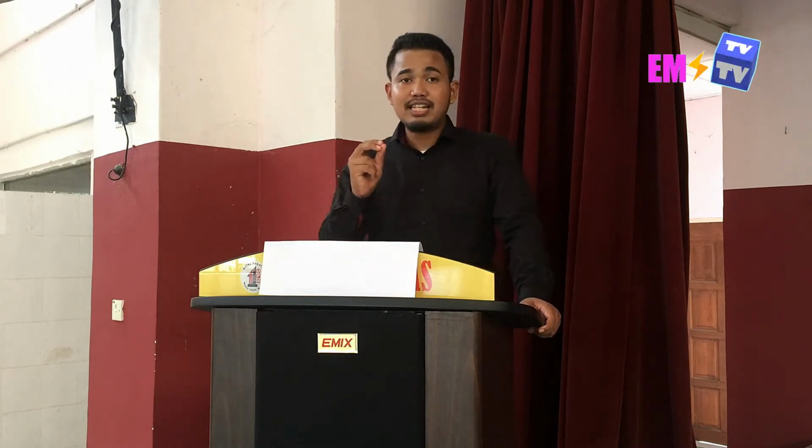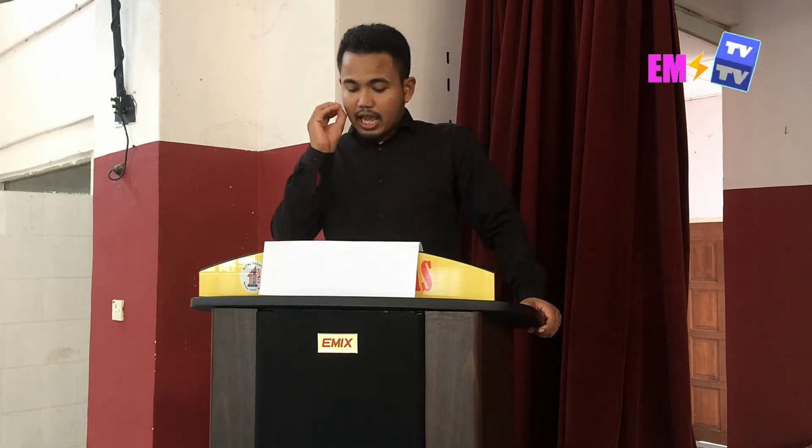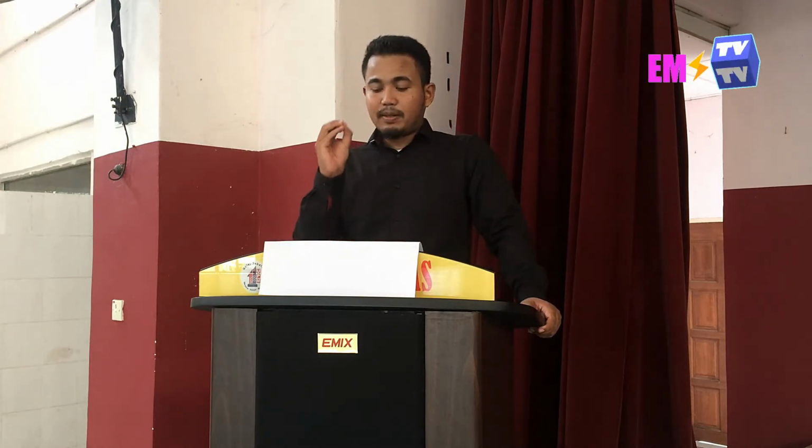LISN, line impedance stabilization network. It will stop the emission on the power lines that is powering the whole test instrument from corrupting the measurement. And it is to ensure the measurement that we make is actually just the emission from the device and not everything else that is connected to the network. Then it will be sent to the receiver, then the result will be compared.